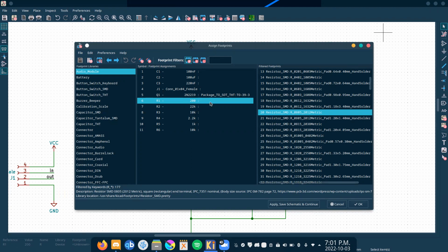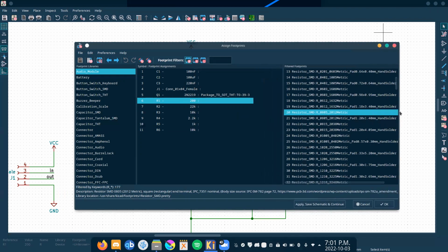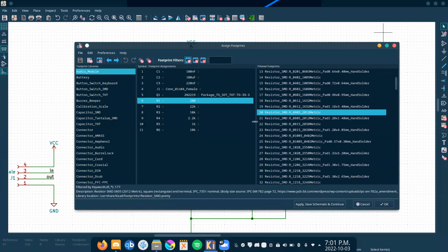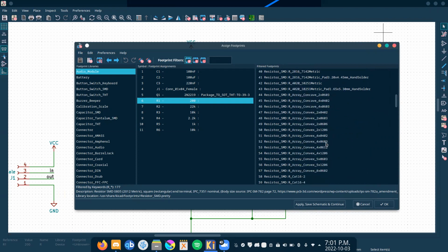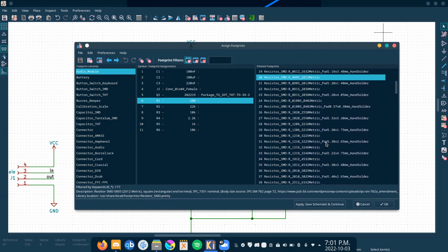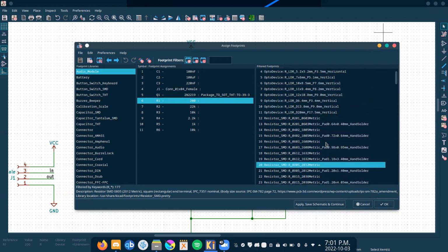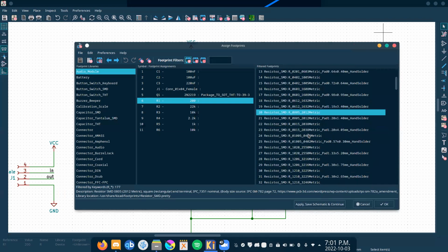Do you have any general rules for picking standard ones? That's something you kind of need to learn by designing a PCB and then trying to find those components on DigiKey, because when I first designed one, I had no idea. Look how many options there are for resistors here. How do you know which one to pick? I started looking at them, and this 0805 is the dimensions in millimeters, I believe.